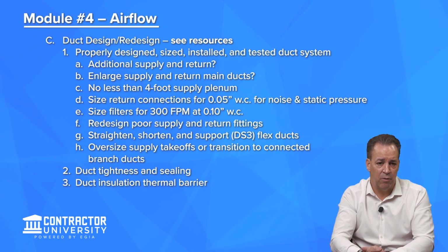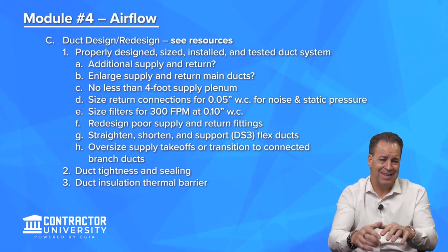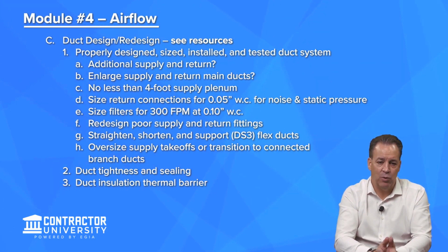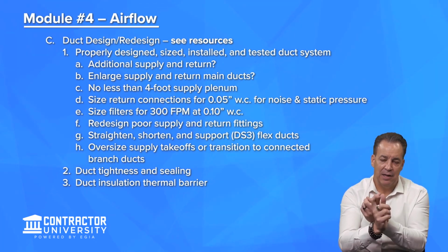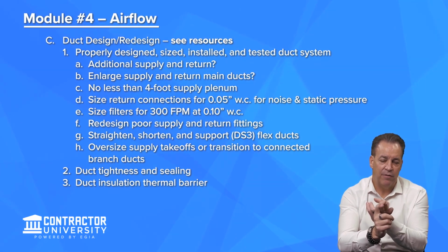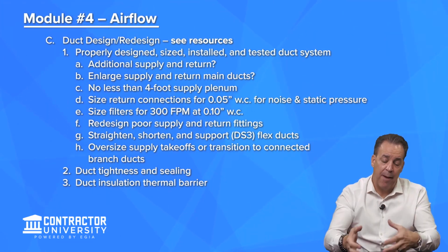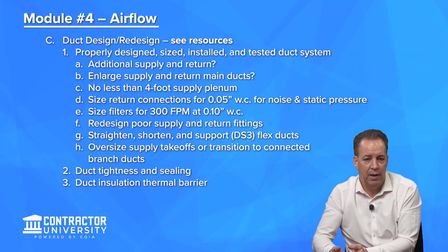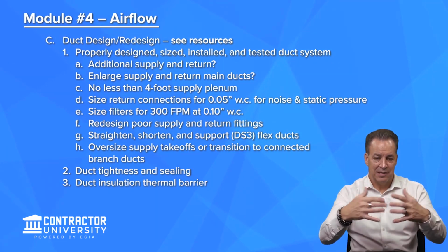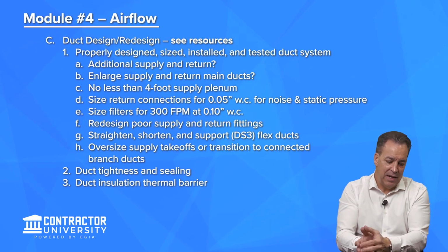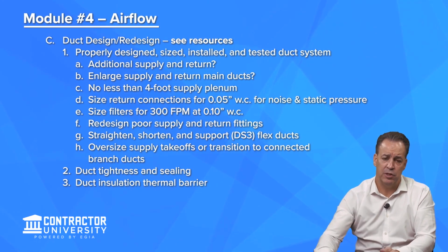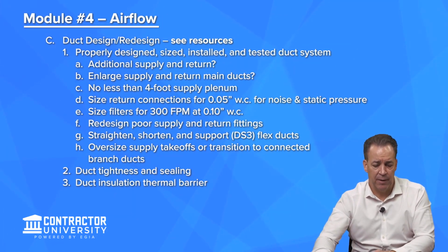And then there's also sheet metal ductwork that was installed years ago that was lined internally as well. Again, I'd recommend getting rid of that because it held on to a lot of dirt. And again, you can't clean insulated ductwork and get it fully clean. You can't clean flex and get it fully clean. So you're better off just replacing that and starting new and then optimizing the ductwork for the new technology anyway. And then giving the customer a better designed, installed, sealed, insulated duct system that is up to today's technology and is going to allow them to maximize the performance of the machines, the high efficiency and advanced technology that they're buying.